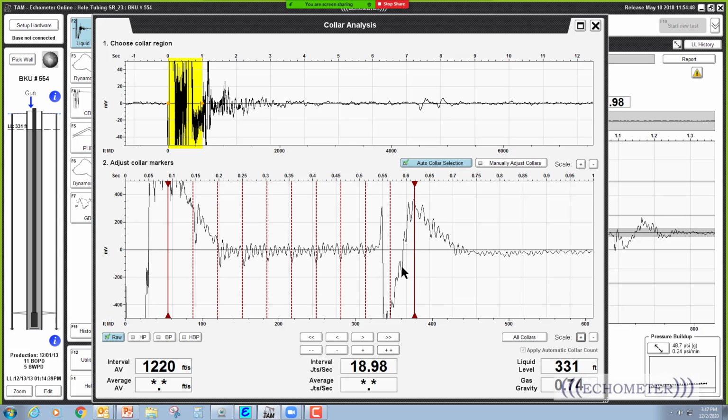But that's an echo. That's the acoustic trace on a high hole near the surface, and these are really hard to see. And so when you go to a well and you suspect there's a hole near the surface, then you have to put a small differential pressure in your gas gun. So see, the well pressure here is like 48.7 psi at the surface. You need to have maybe 50 psi more, maybe 100 psi in your gas gun when you shoot this well, or you're going to create too much noise from the shot going. See how the shot's off the screen right here?